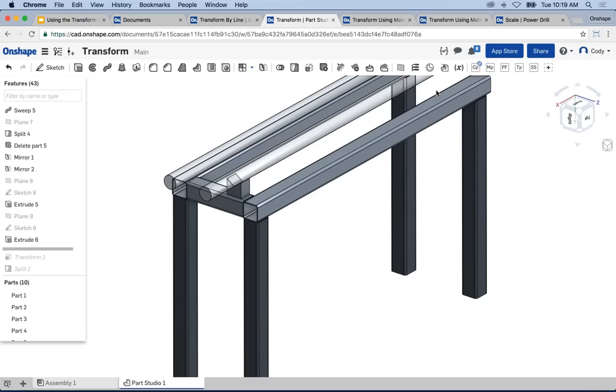At that level, you want to insert those instances at the assembly. And we have lots of pattern techniques to help you handle multiple instances of a part. Another example I like to give is putting a bolt in a hole. If you have a dozen bolts that go into your assembly, it's best to do that at the assembly level, not in the Part Studio.